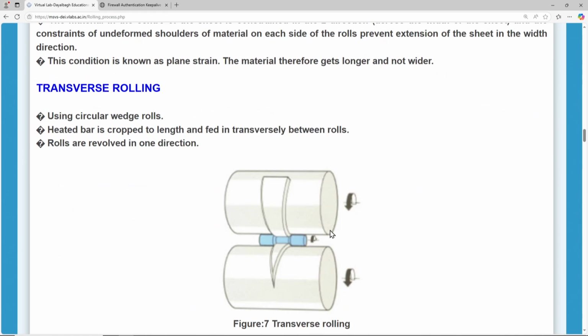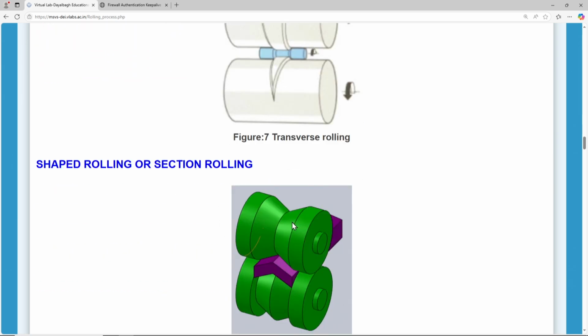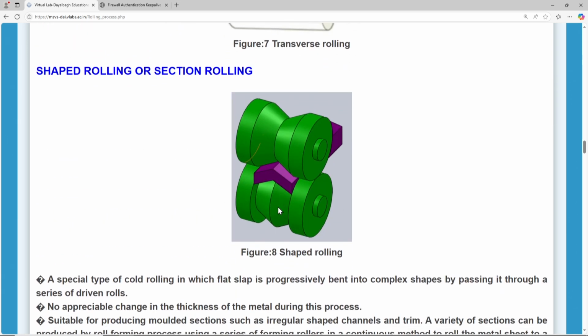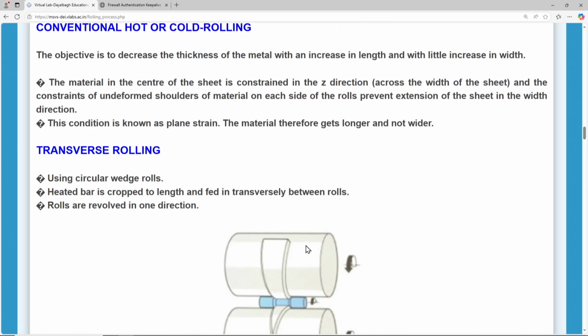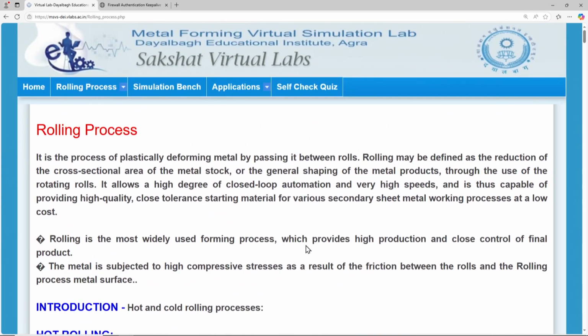Multiple rolling systems are being shown here, and it's a transverse rolling process that helps to develop the wedges, that helps to develop the components with the varying radiuses as well. This is a transverse rolling process. So shaped rolling sections are also there, in which a specific shape could be gotten in one go. For example, railway lines are also produced using the rolling process. So let me come to the types of the rolling process. It is showing ring rolling, thread rolling, and wedge rolling.